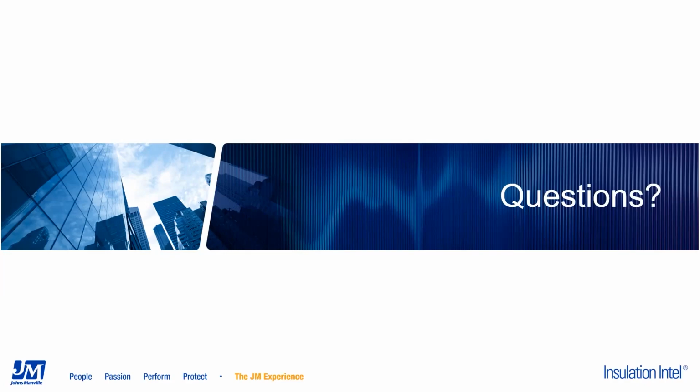All right, thank you guys. There's also a question, acoustic performance and comparison of double stud versus staggered studs. Could you please provide further explanation as the staggered studs do not touch and should have less transmission versus double studs in typical wood stud wall? Yeah, I'll take that. So the issue with staggered studs is that they share a top and bottom plate.